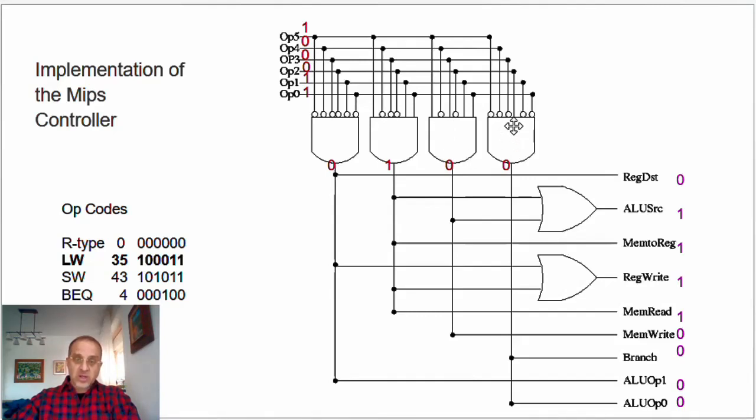And also here, I have inverted. Let's say, for example, the first one, which gives me a 0, which is on an AND, it's going to give me a 0. So I'm definitely going to get 0, 1, 0, 0, and then that is going to give me a 0 on this line. The 1 coming through here into an OR is going to guarantee me a 1. The 1 also goes straight through to here. That's going to give me a 1. The 1 also goes to this OR, that's going to give me a 1. And the 1 also goes to this, and it gives me a 1. So that gives me all these 1s.